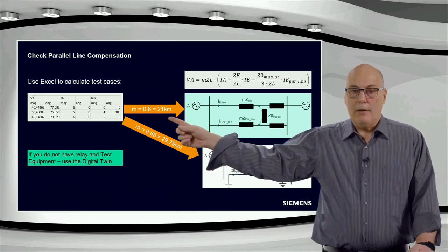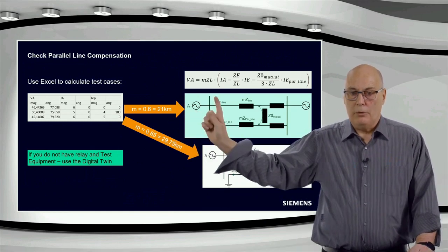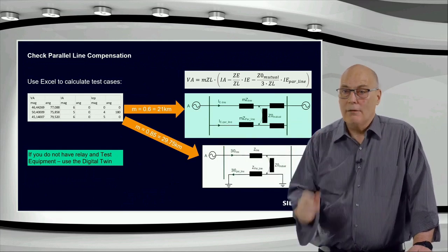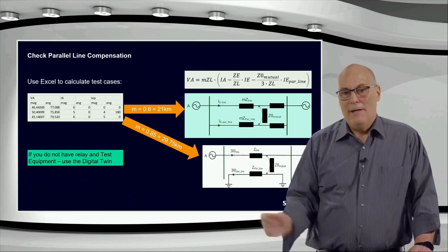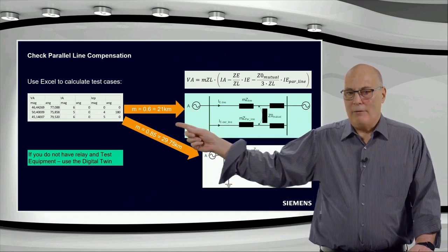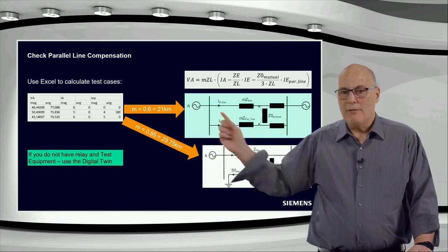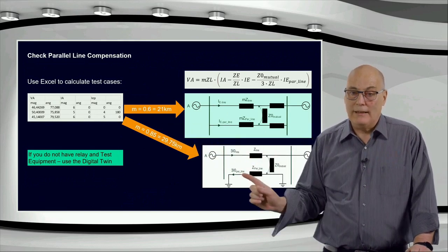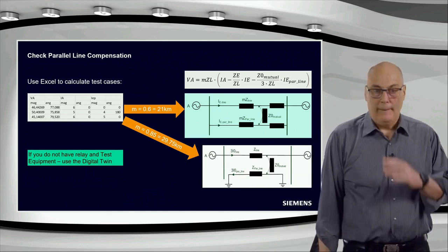You see, we have the same current in the third test as in the first test on a protected feeder, but a smaller voltage, and the fault is further away. Remember, for the first test, the fault was at 60% and gave you 46 volts, and for the bottom test, the fault is at 85%, and you still get a smaller voltage. That is the significance of the parallel line infeed.